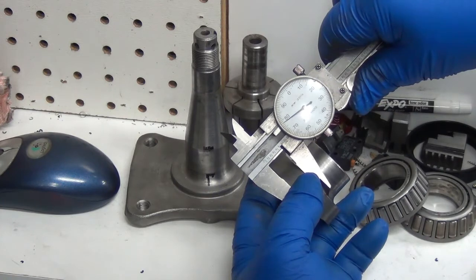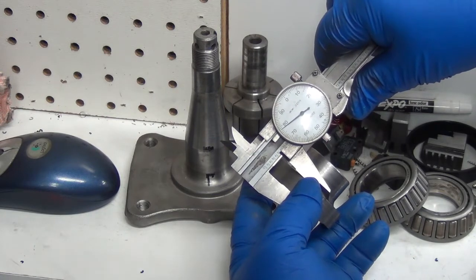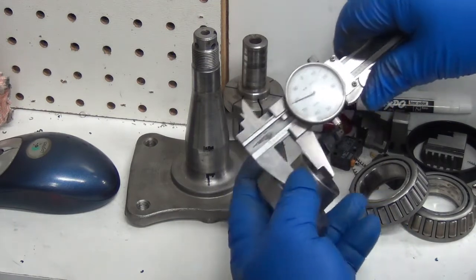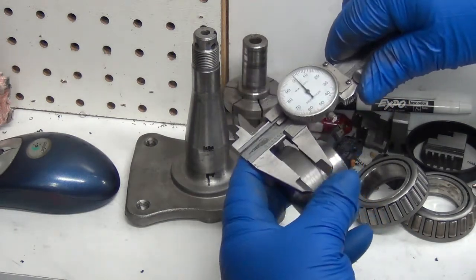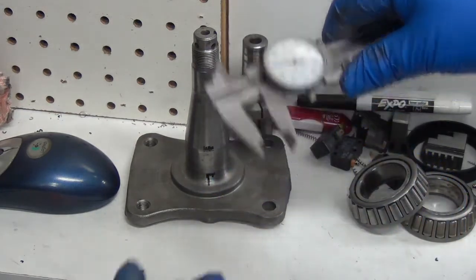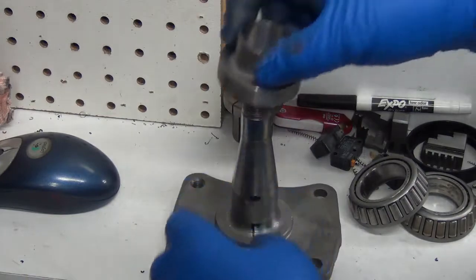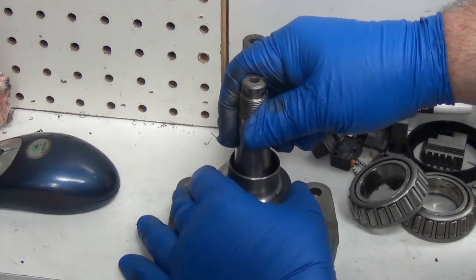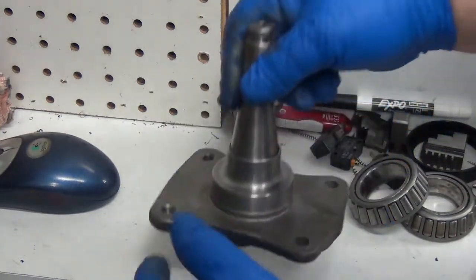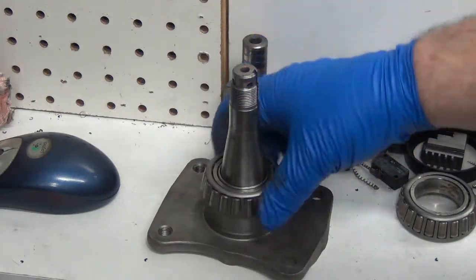But one thing I did want to check too here was, all right, I'm 2 thou shy of my 480 mark. Okay, so without changing anything else, I could go in and just change the DRO, since the way I checked it wasn't extremely accurate. Now I know that with those cut loads and everything, I'm going to come up 2 thousandths shy. So basically I'll just add 2 thousandths to the DRO, and that will give me the offset needed without affecting the difference between the tools. So there we go.